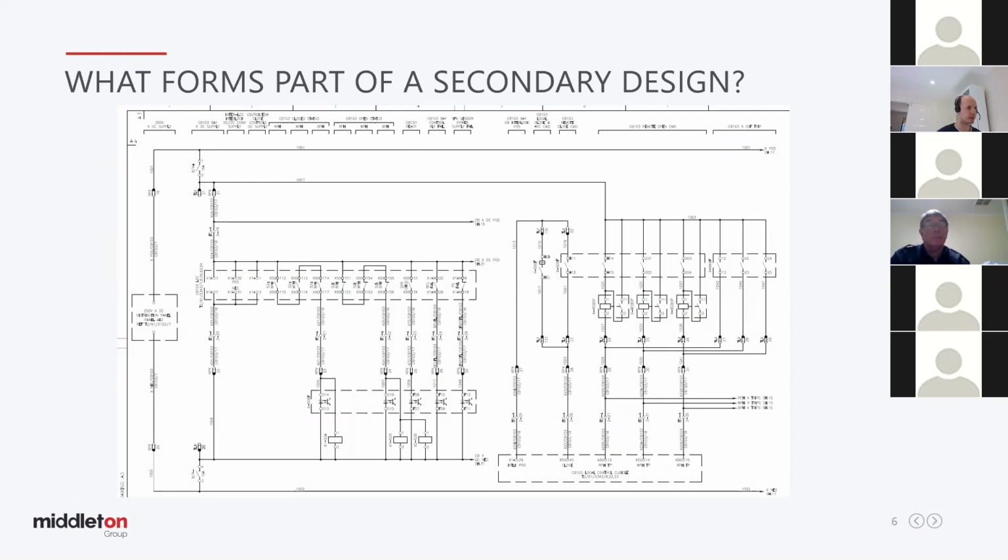If we talk about a terminal station for a utility, for example, a 220 to 66 kV terminal station with say 5 transformers, you're probably looking at a couple of thousand drawings in the secondary realm for that site. Depends on the vintage and the type of site. The most I've ever worked on in one particular project, which was a complete brownfield upgrade from AIS, air insulated switchgear, to gas insulated switchgear, had about 20,000 drawings. So that was a massive undertaking.